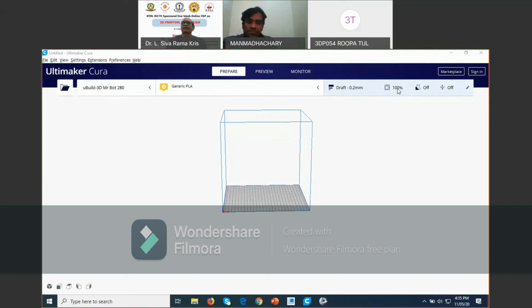One question: how to understand infill patterns for turbo machinery design requirements, for example an impeller? Infill percentage means the material filling percentage. Suppose you require a solid part, you have to choose 100% filling. Suppose you require only the shape, you can choose only 5% filling also. Depending on your application, you can choose your infill percentage.